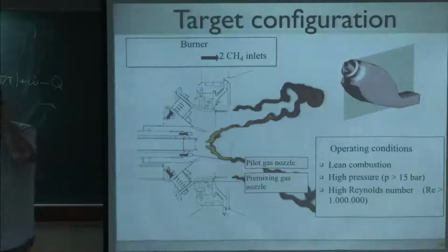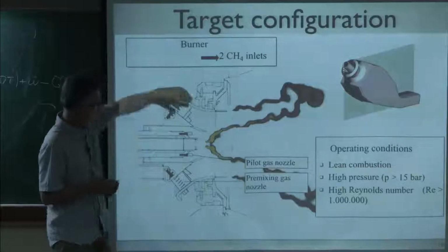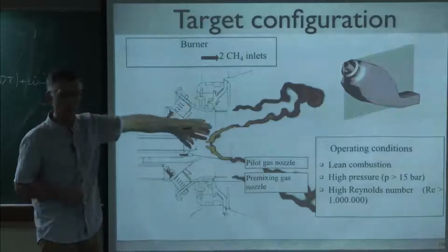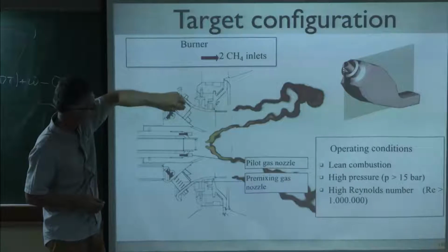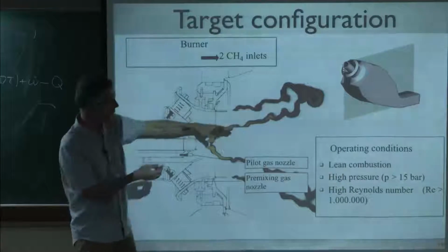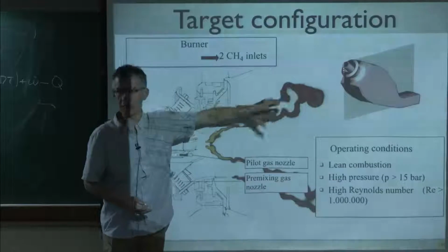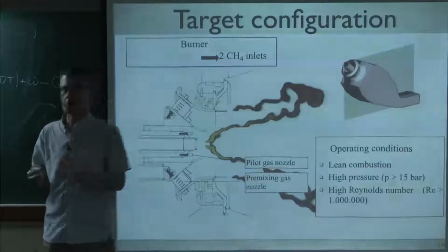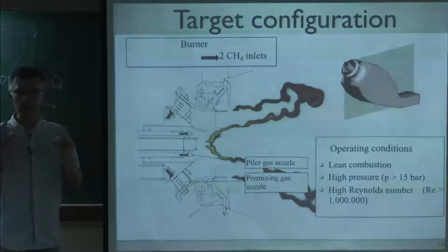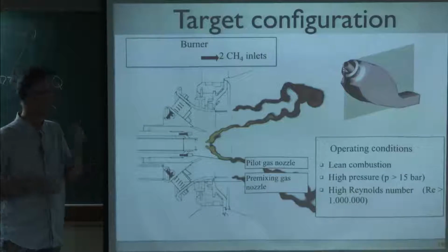And the guys who have imagined this system have the following idea. Here, you inject a little bit upstream of the chamber. So you hope that air and fuel is going to mix and lead here. This is swirl, so these gases will go like this, and they will burn here in a premixed flame. And 90% of the power is obtained this way. So it's almost premixed. Only almost. You cannot really say it's premixed. If you run it in premixed mode, you won't get the right result.